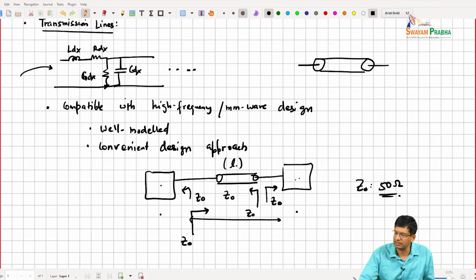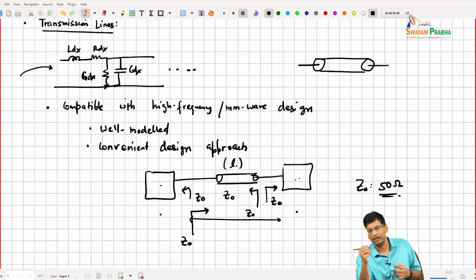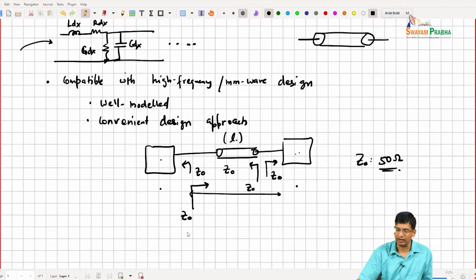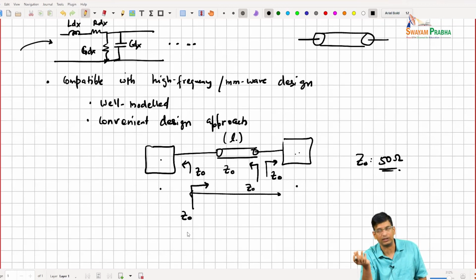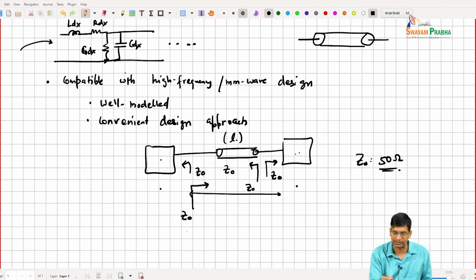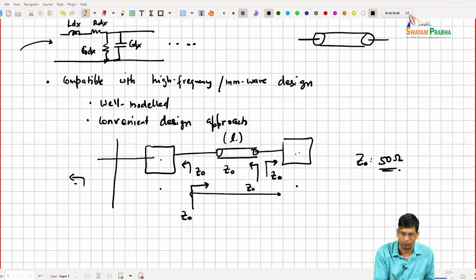There are some limitations, which is that on the chip, having very high impedance transmission lines is challenging. So you can go up to 70, 80, 100 ohms, but if you're building really high impedance lines, that is challenging. And the second part is that when you interface with the outside world, then if you're interfacing with measurement equipment, etc., outside your chip, then that measurement world is still 50 ohms source impedance, for example.